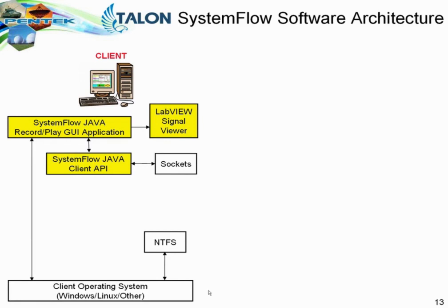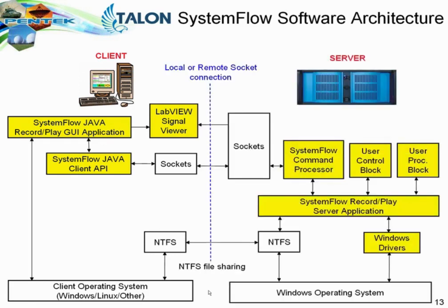So, for example, one of the screens that comes up are the parameter screens for setting up your input channel. In this case, an analog input channel where you'd set the bandwidth, decimation, the source, triggering modes, polarity, sampling rates, and so forth. This can all be set up and configured just by entering the parameters or pulling down selections. You click Apply, and then you're ready to go on to the next channel setup.